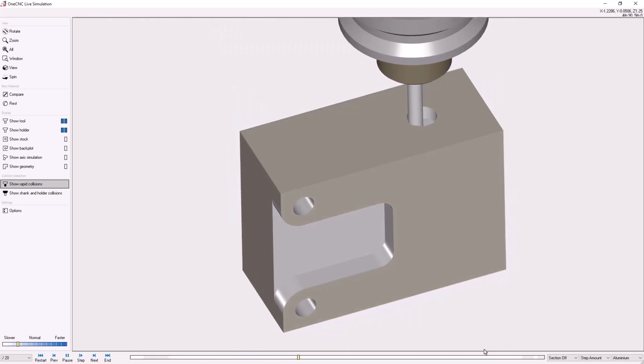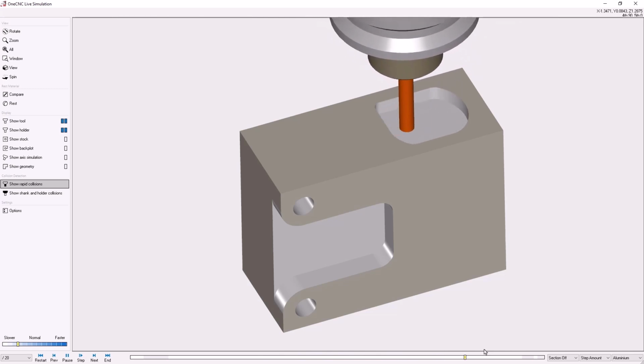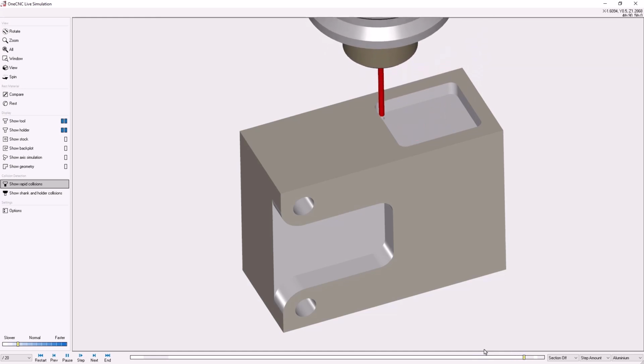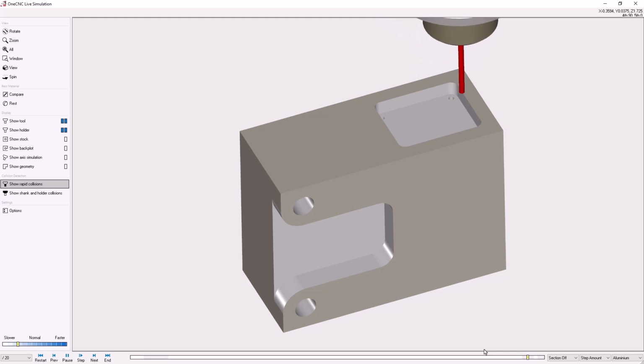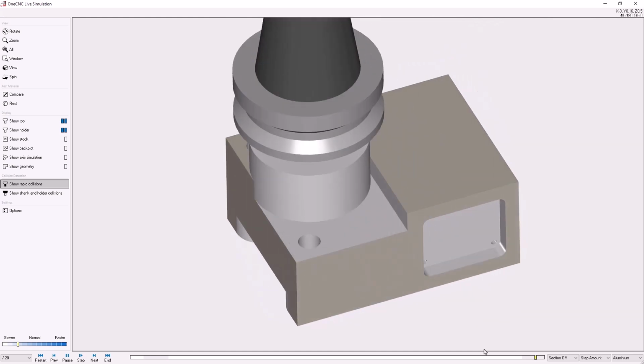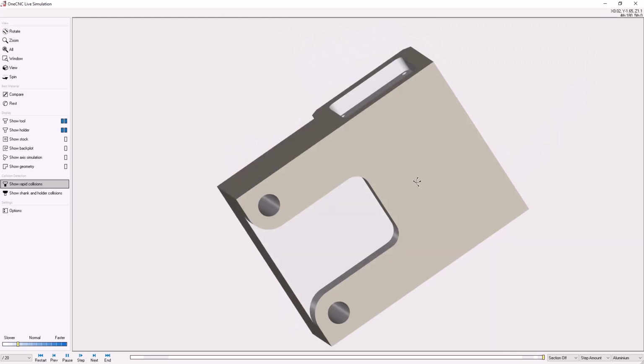So what we're looking at now is our toolpath simulation. We've already machined side 1. Now we're machining side 2. Here's our closed high-speed pocket operation, and we're drilling those 4 holes in all 4 corners using that 3/16 diameter drill. When that's done, we're going to index over to side number 3. There's our shell mill, and there is our chamfer operation.